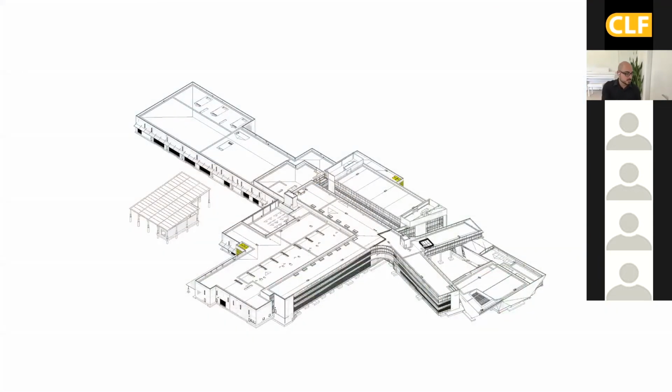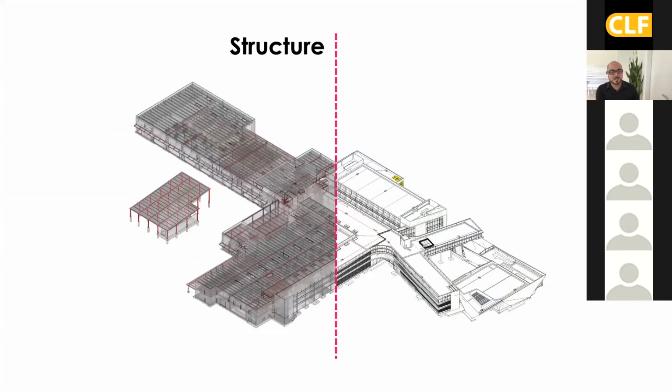So when we start a whole building LCA, we basically want to divide the model into structure, the structural model, and then the enclosure model. After that, you could also include interiors. For LEED, you're not required to include interiors, but optionally you could do it. And hopefully over time we get to do more of the interior models too, because it could be high impact. But the minimal would be to have the structure and the enclosure.